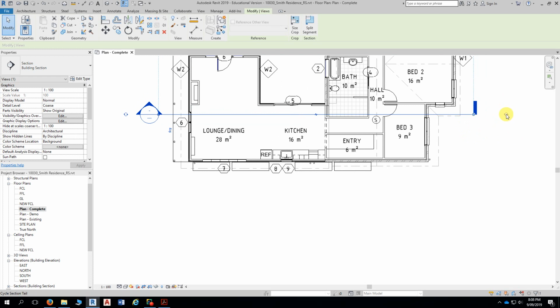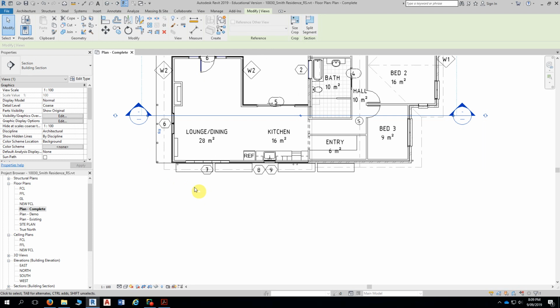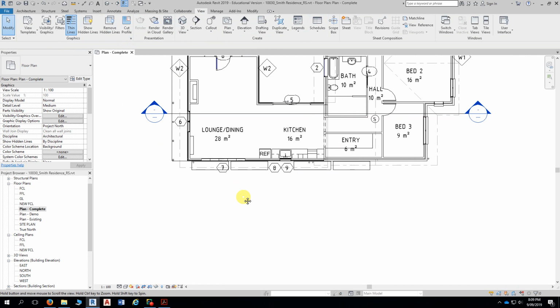If you click directly on that, it will actually change the tail to nothing to a head, which is what we want. So we need to have this head on both sides. And while we're doing that, if you just bring the head in slightly on each side, like so, and then you can hit the escape key to deselect.